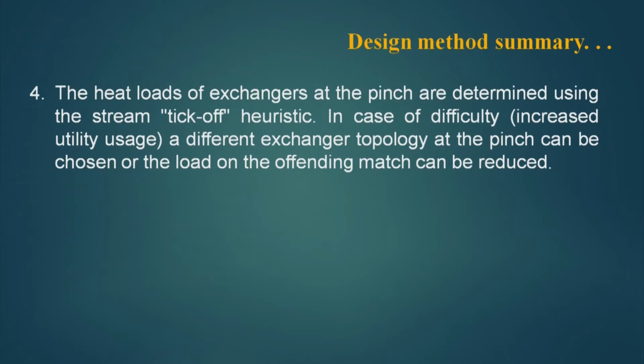In case of difficulty, that is when we see an increase in utility usage, a different heat exchanger topology at the pinch can be chosen, or the load on the offending matches can be reduced. Now, based on the tick-off heuristic, many problems can arise, and to solve those problems, we can select different matchings, or we can reduce the load of a particular heat exchanger which the tick-off offers.